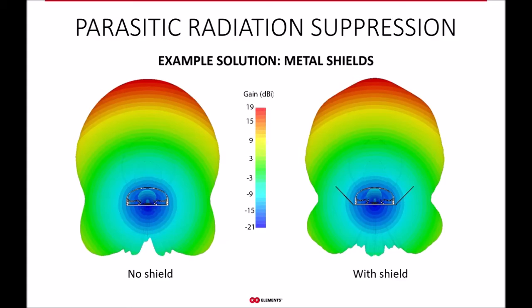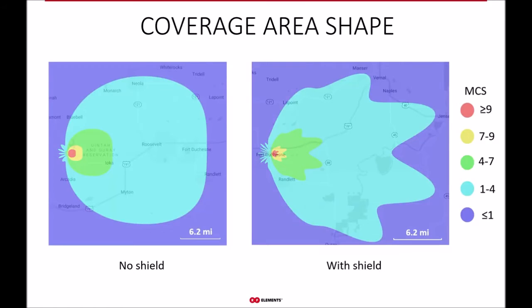So the conclusion for the shields is that they will really not help you mitigate the side lobes. As intuitive as it sounds, one would think if I put that shield around it, surely it must be doing something. But in this case, this intuitive understanding does not apply. Some things in the art of engineering or in physics in general are just weird. Some are intuitive, some are not, and this one is definitely not. The conclusion here is that the shields, unfortunately, do not help to mitigate the side lobes.